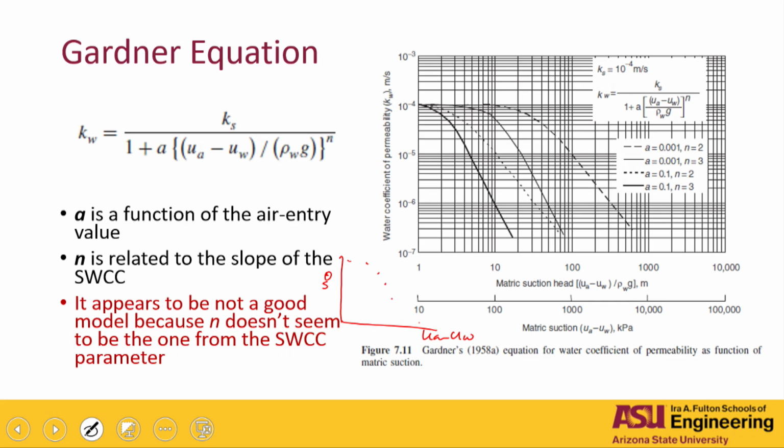Then you do a solver or nonlinear regression analysis. You input your porosity there, or if it's the degree of saturation here is 1, and then you fit a function to that, right? And in order to do that, you're going to need fitting parameters. The fitting parameters for the Gardner equation are A and N. For van Genuchten, A, N, and M, so 3 parameters.